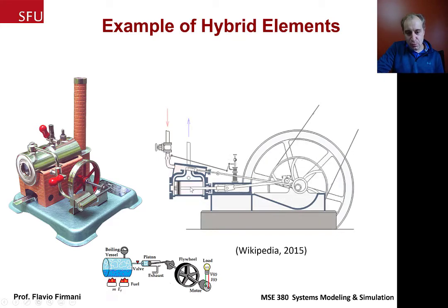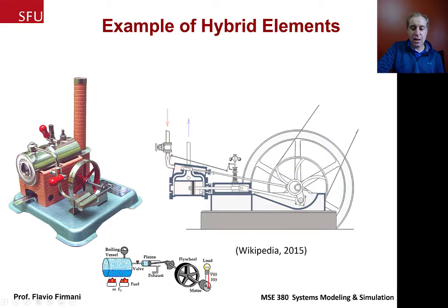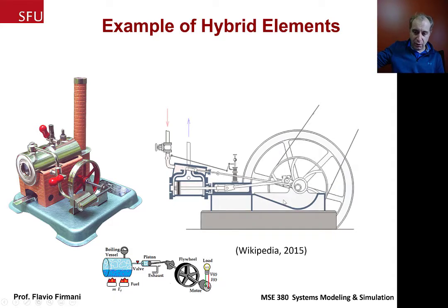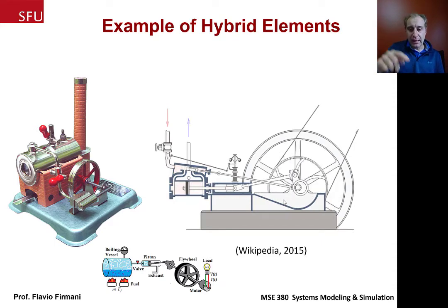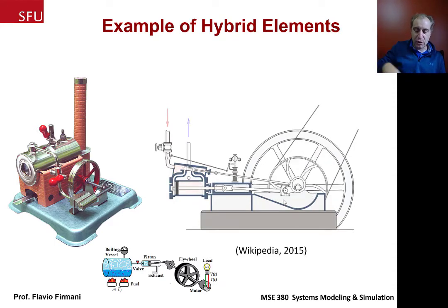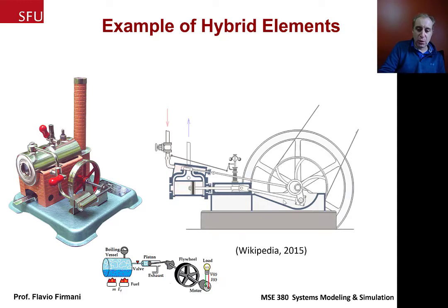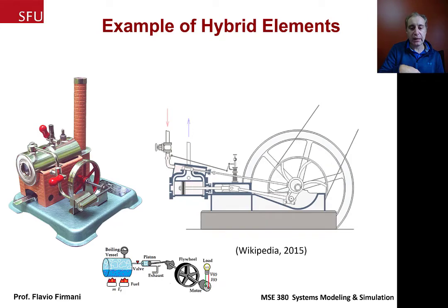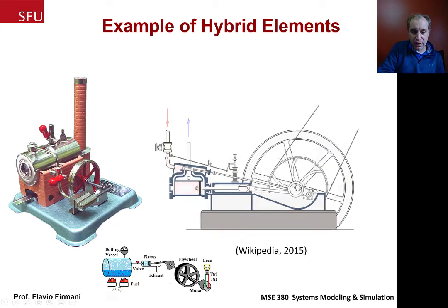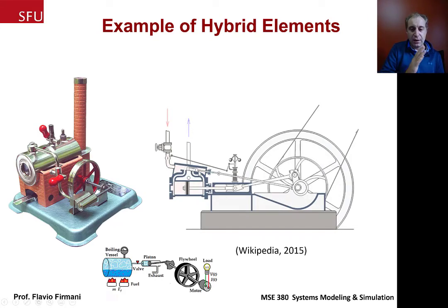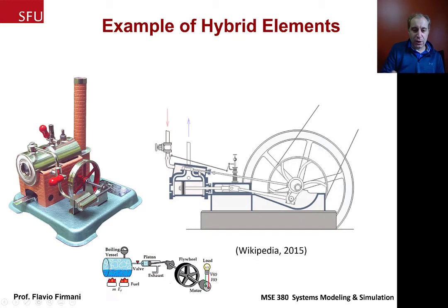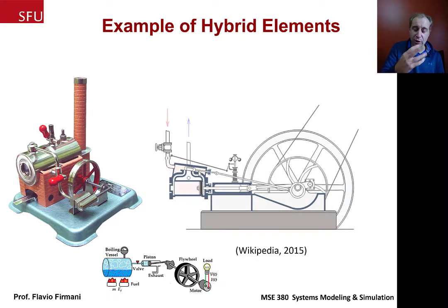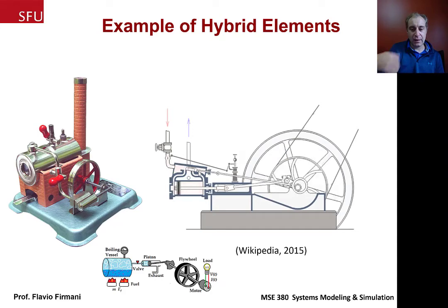As it moves, the piston is connected to a slider crank, so the crank will rotate a flywheel or a pulley, and it will turn around and the piston will back up. Again, the steam will go in again, and there is a small valve in this example that opens and closes for the steam to go in and out.